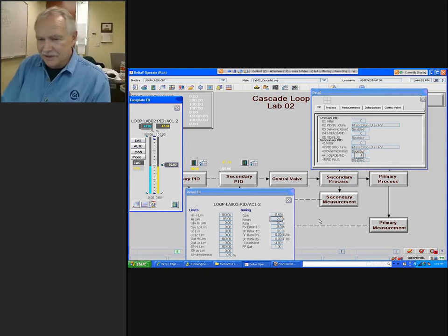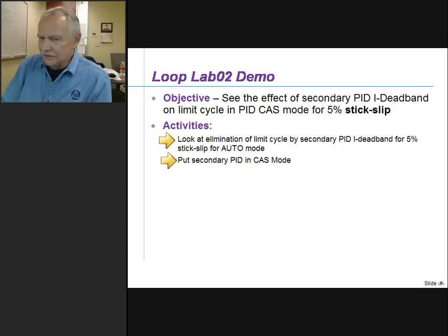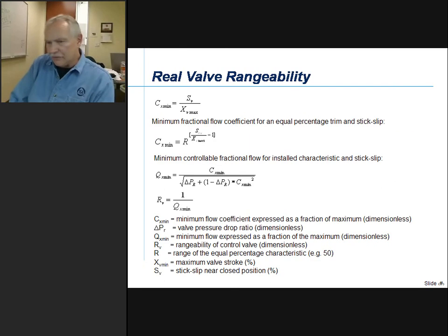There are a lot of statements on rangeability that are made, and I think an awful lot of them are very misleading, because the piping valve manufacturers, when they're selling you a rotary valve, it has a high flow capacity. Particularly if it's a full bore ball valve, you've got the whole cross section of that valve available for flow, or it's a butterfly disc valve, and it's 90 degrees open, and except for the disc, you've got that whole pipe available for flow.